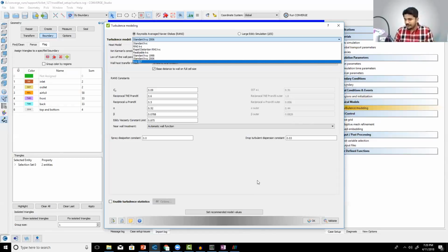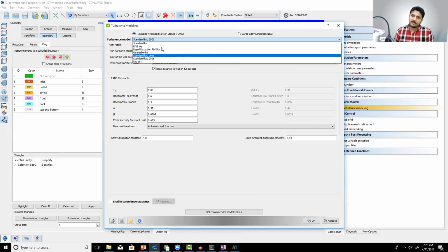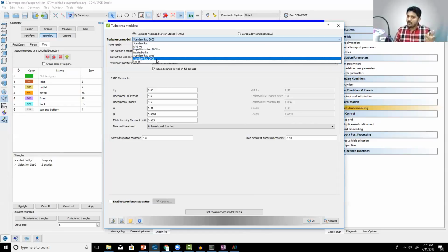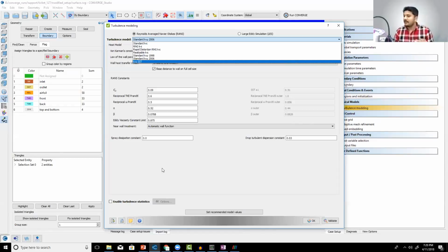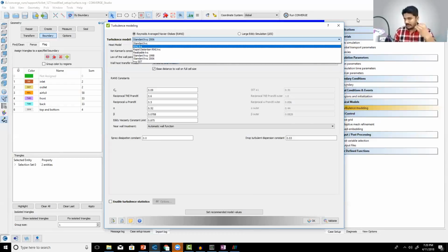So how do you fix it? Well, you can use a K omega model with automatic wall functions and maybe reduce the mesh count a little bit. But then if your Reynolds number is huge, even that mesh resolution that you need is going to be very small.